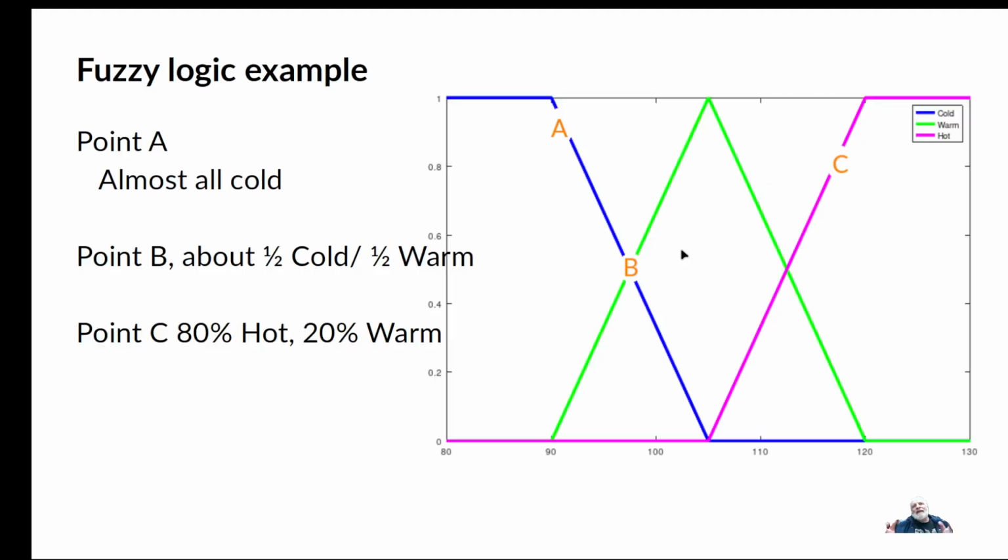This is what we call tuning. I didn't put that in the slides, but you have to tune your fuzzy sets to get the system to behave the way you want. In this case, I only have 3 of these sets: cold, warm, and hot. But we could add 2 more or 5 more, or as many as you feel you need, and then you can tune the system by adjusting where these lines cross in here.